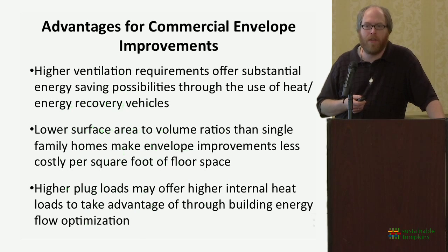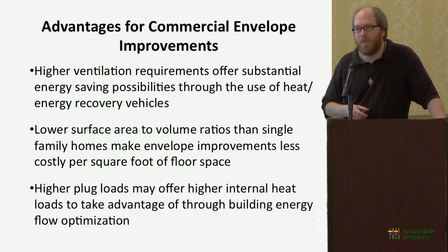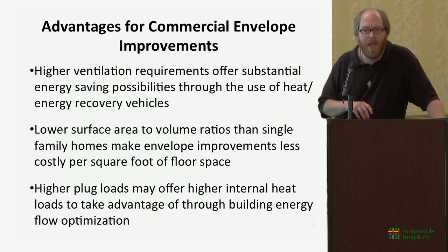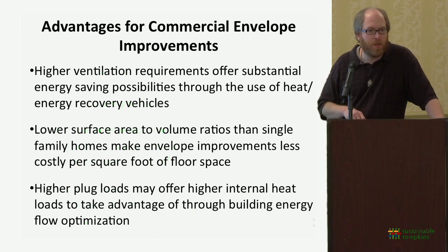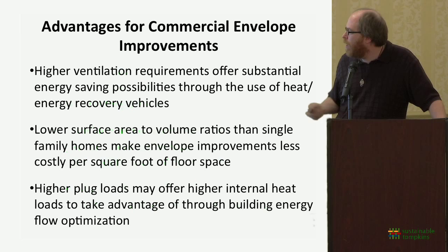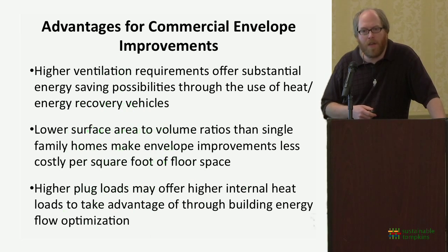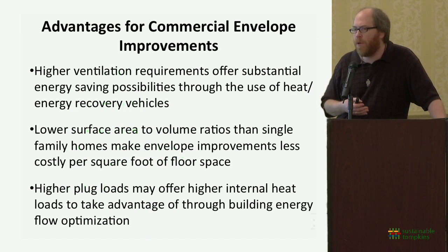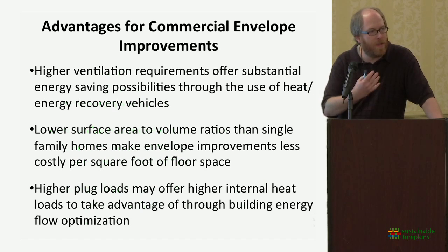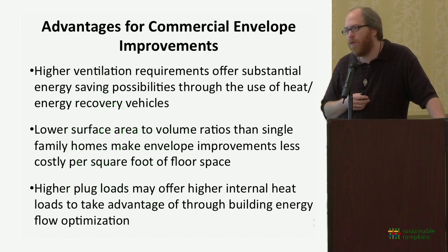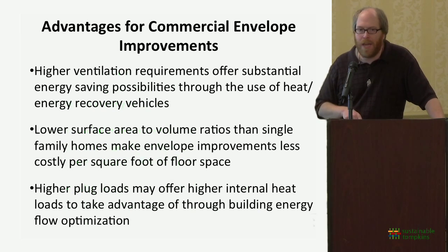Simple surface area to volume ratio: a big commercial space has less surface area per volume than a smaller home does, and therefore envelope improvements can be made for a lower cost per square foot of operational floor space. The other piece is that you can, depending on the nature of your systems, have high plug loads. If you have an awful lot of computers or other types of equipment running in your office space, all of that equipment is giving off heat that you can then recover and move around in your space if you can optimize it, and you can take advantage of those plug loads as part of your heating system.